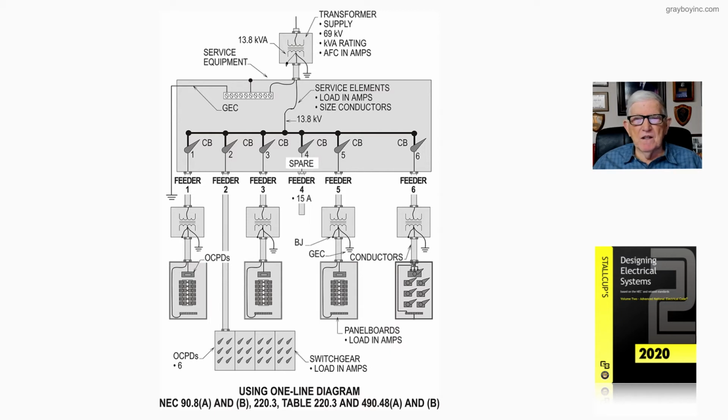Pardon me for saying that, it is feeder 6. You can see that the components in there, the shape of them, the way they're drawn, they're for the higher voltage. It's over 1,000 volts, while the other 3 panels you see there are less than 1,000 volts, and then you have the higher voltage when you get into your feeder 2.